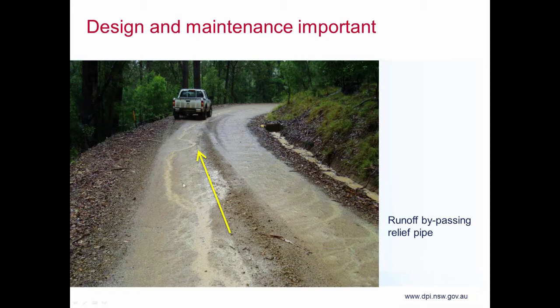One thing, a little tip here, is that these roads obviously look very different when they're wet compared to when they're dry. So the best time to go and inspect your drainage is during a rainstorm. That's typically what I would do, go out when it was raining and see which way the water was running. And that's something I'd recommend that you do.